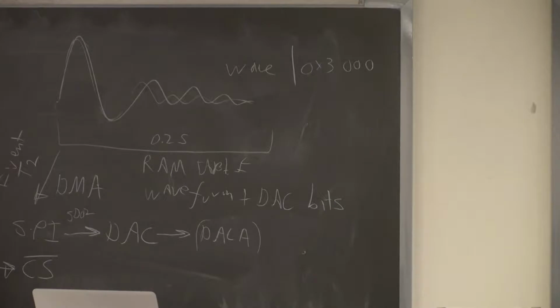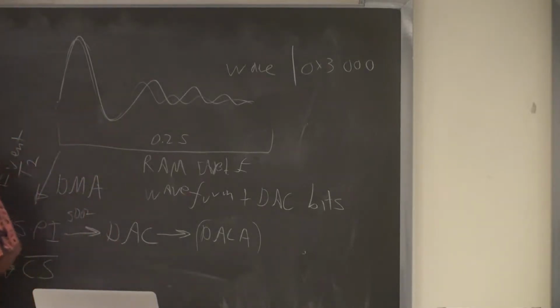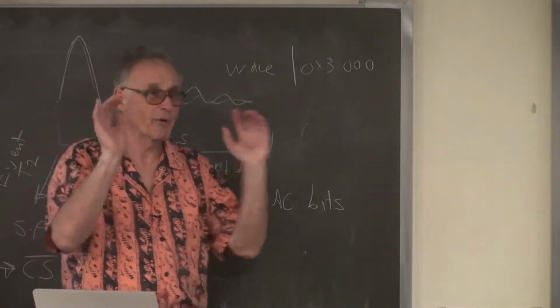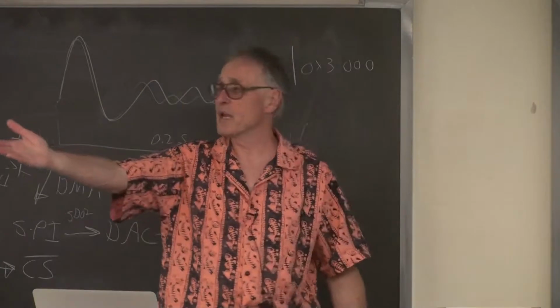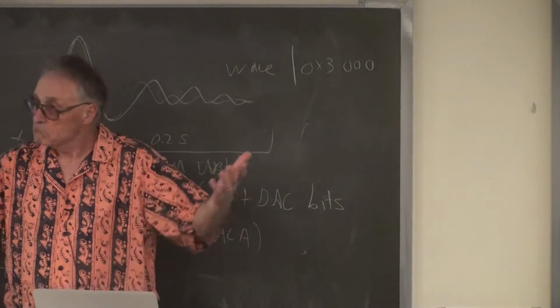So you're quite right. That would exactly work. And then the question is, if there was a one sample offset between the two channels, would you know? And if it's at 10 kilohertz, you wouldn't, because your acoustic time resolution, if you're very good, is probably 5 milliseconds. So you wouldn't notice it, and that would work exactly that way. You'd interleave the control words for channel A and channel B in the table, and it would play both channels alternate samples. So you'd have to sample twice as fast. It means the table would be twice as big, but you put it in flash.